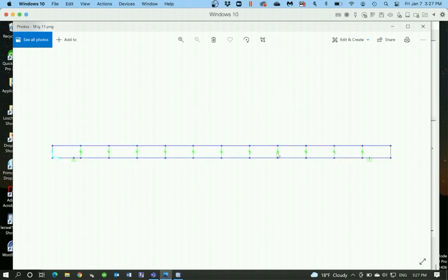And we take those values and use them as the input for a frame analysis, a Vierendeel truss type analysis, where these springs represent the connectors and they have shear deformations, which correspond to that graph you just saw. The blue lines are the concrete withes, the withe elements.